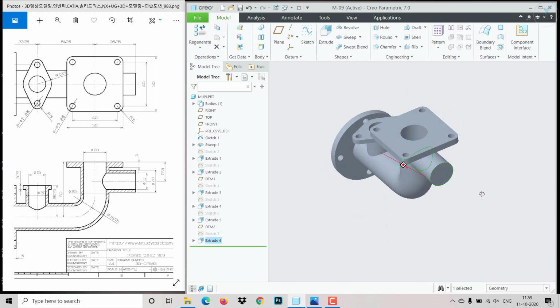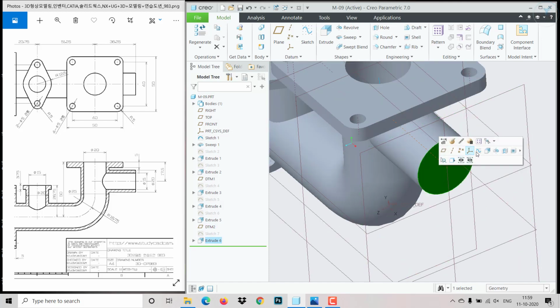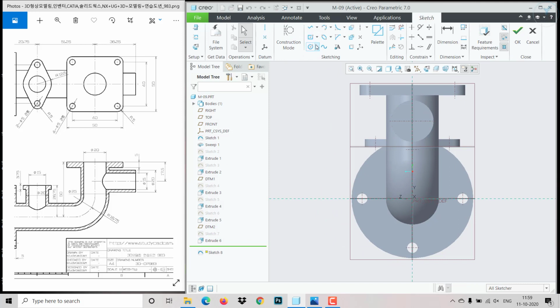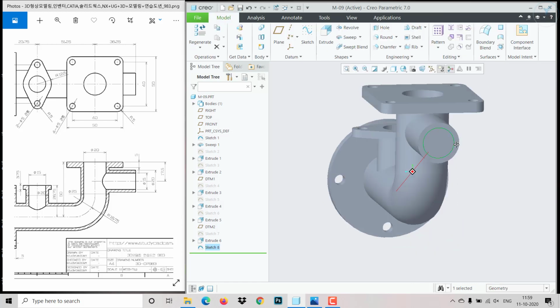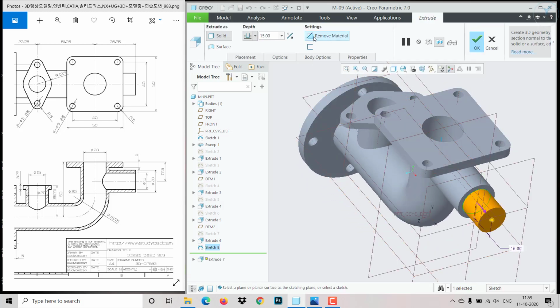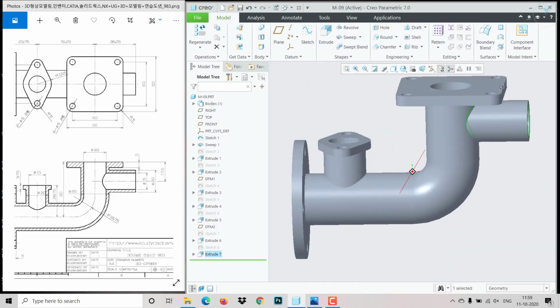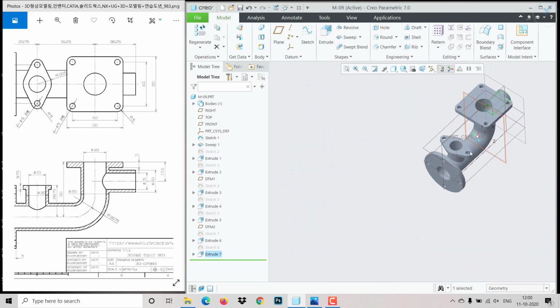Now click OK. Now on the same plane we need to make another sketch, that is the inside one, that has to be having a diameter 15. So concentric, select this, position it, giving diameter as 15, enter, click OK. So extrude, remove material, flip, up to surface, select the inside one, so it will remove up to that. So like this way we can complete it over here.